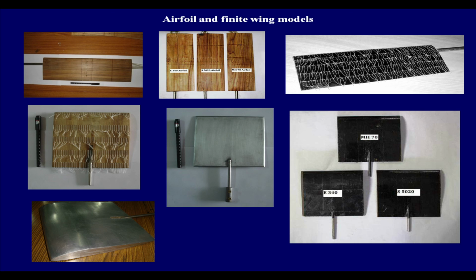Will you be better off if you go for a bigger test section where you can accommodate a geometrically similar model, but where the chord length just doubles, and you still live with a fabrication method where the maximum error is 1 mm? So, straight away your geometric error comes down by 50%. That is one part of the story.